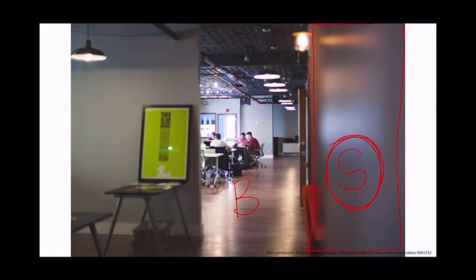Anyhow, if you have this office building, now when you're trying to figure out how big it can be for a given construction type, you no longer probably can use B, because most likely it depends on the construction type, but most likely the S is the one that's more restrictive. So if the S is more restrictive and it says you can only be 3 floors instead of 5, you have to use the S if you chose the non-separated, or you have to go to a higher level of non-combustibility in the construction.